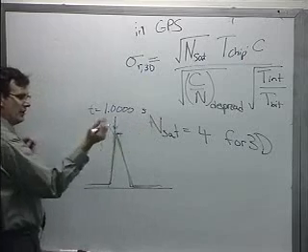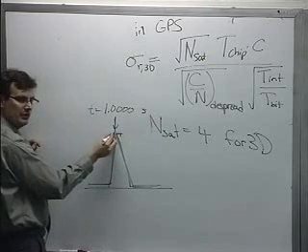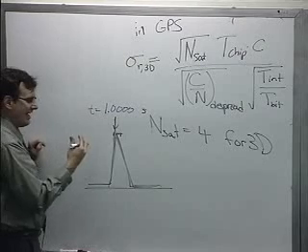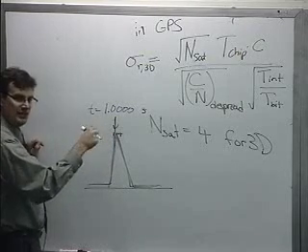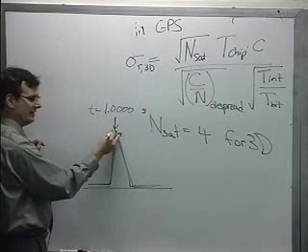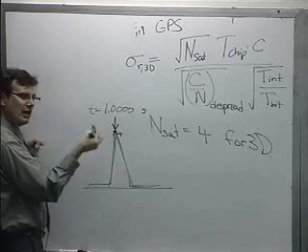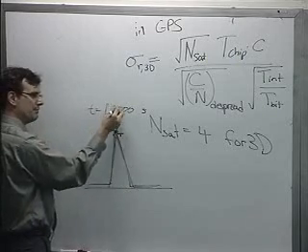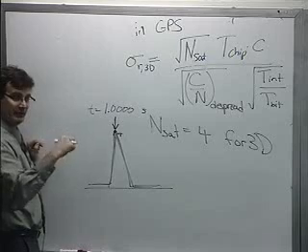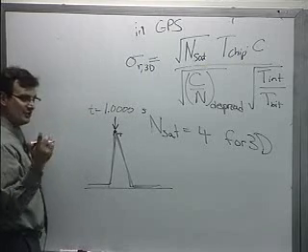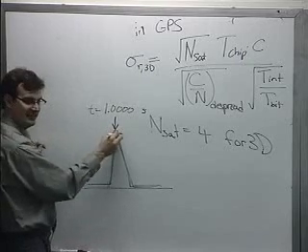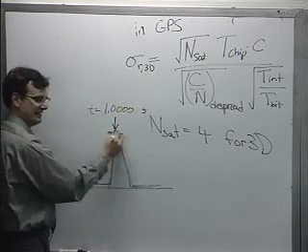If I slow it down a little bit and this drops just a little bit, then I know that I've undershot it. So there's a special receiver structure that you can use to maximize that point. And if you have a very accurate clock in your GPS receiver, you can pin this beyond the resolution of your sampling hardware. The only problem is that it assumes you have a very clean signal, because as soon as you introduce some noise into that algorithm, the thing starts dancing all over the place.